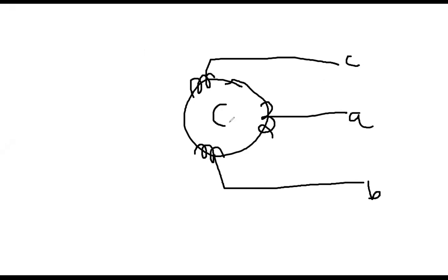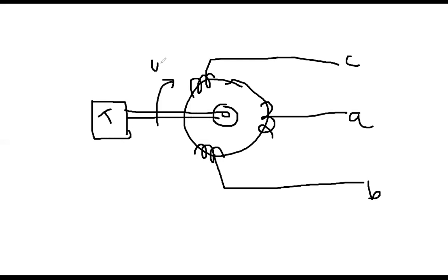And in between, there is the rotor circuit to which the shaft is connected. And again, the shaft is connected with the turbine T. Okay. And then this is rotating at a certain speed. Now the magnetic field is basically mounted on the same body. For example, here is the North Pole and here is the South Pole. This means in this case, the magnetic field is mounted on this body to which the shaft is connected. So when this shaft is rotating with the help of the turbine or prime mover, the magnetic field is moving.